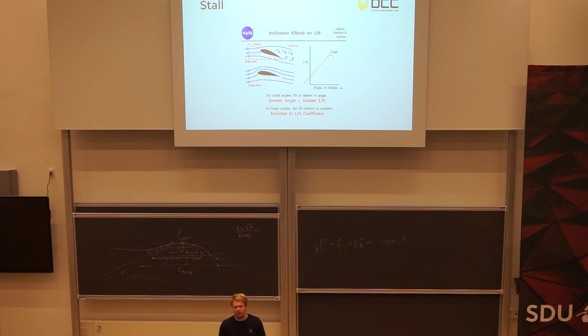But the thing that is very acute for airplanes is that you can notice it. You get a change of pressure on the wing itself. So you could have special things that monitor the pressure on different places of the wing to notice that, oh, we're getting some separation.